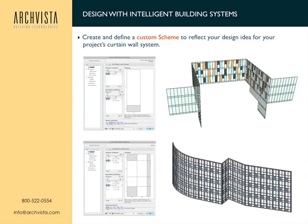So in this case, a curtain wall system, for example, the first thing we describe is the system by which the curtain wall will be defined. So the top is the glazing, and the bottom is an opaque panel. And as you see, that simple panel, once it's extruded and drawn in 2D, creates a system that follows that very nature of what and how it was created. Now, even though this is a system that's very regular, we can actually reach into any one of these panels and change the color and change the type, as I'll talk about in more detail in a second. But we can also define very specific patterns that get repeated within a system to whatever our design intent may be.